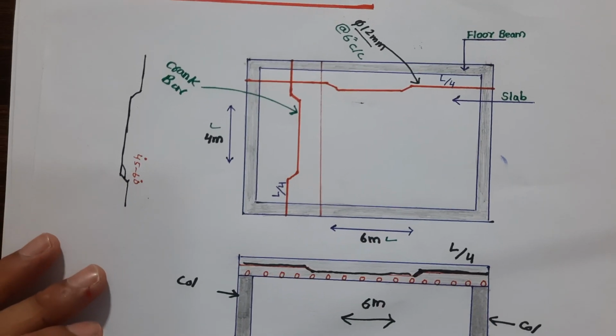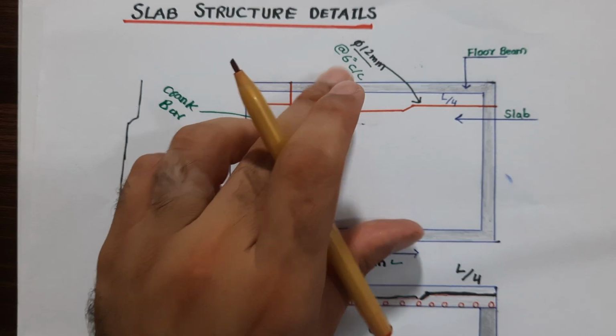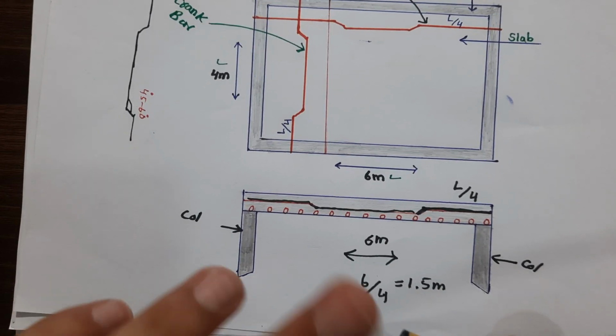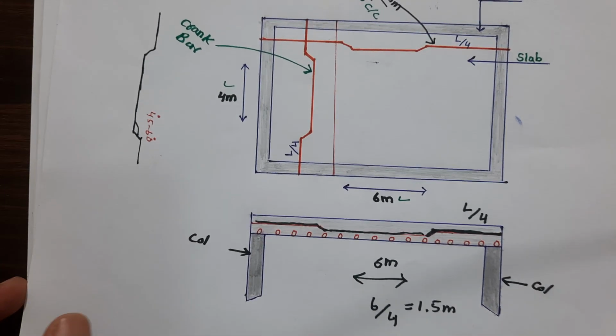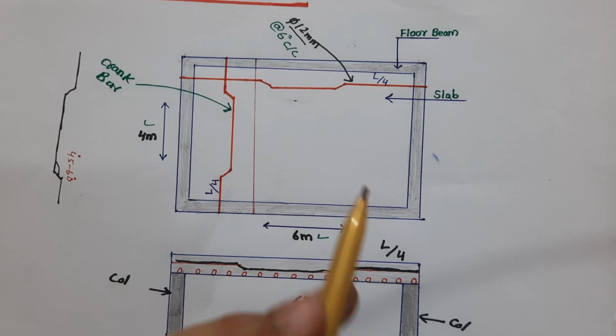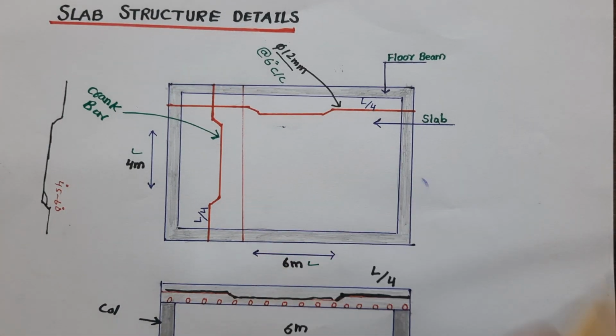Therefore, the steel reinforcement dia should not be less than 12 millimeter with a spacing of 6 by 6 inches. To resist negative bending moment, you should provide extra steel rods. Next, remember one more thing: if you need to provide lapping length, lapping is not allowed